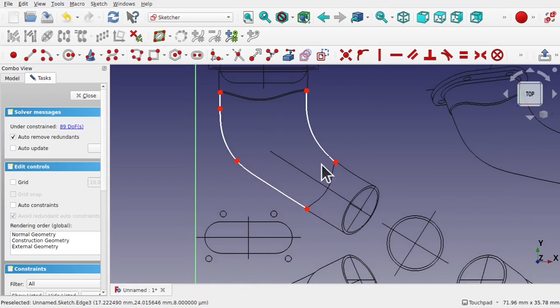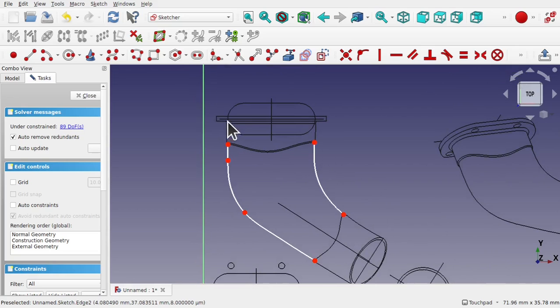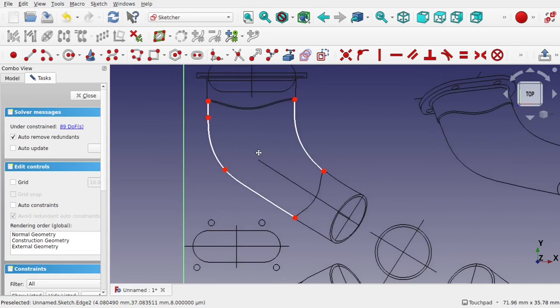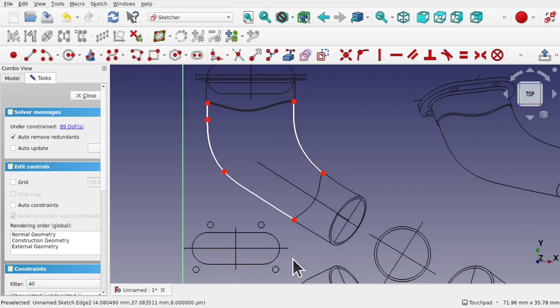We're now going to extend these lines out and attach them to some kind of line along here that we can change the distance with, because we need to actually create this profile, attach it to this point, and create this profile and attach it to this point here. So these will be individual sketches. Let's create the lines. Let's make sure our auto constraints are on. So when I click that line, if we hover over that point, we get the coincident constraint, and we come out to here. And we do the same with this one and come out to here. Escape that.